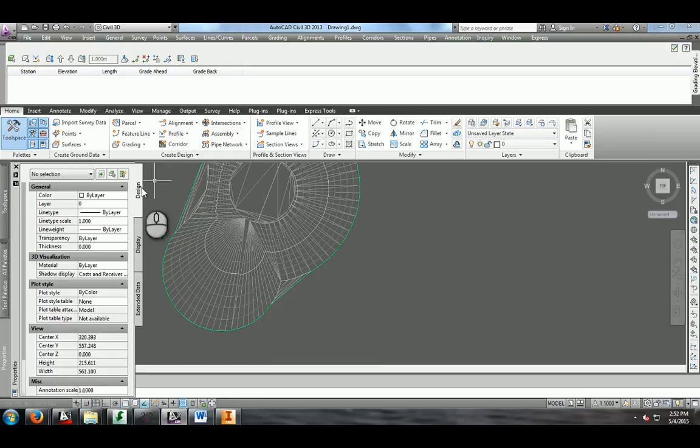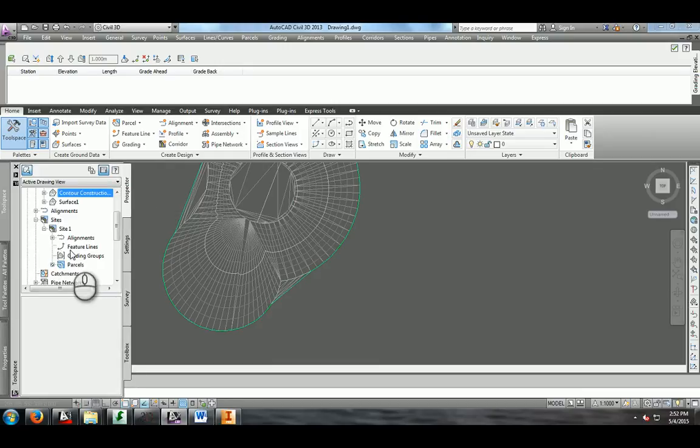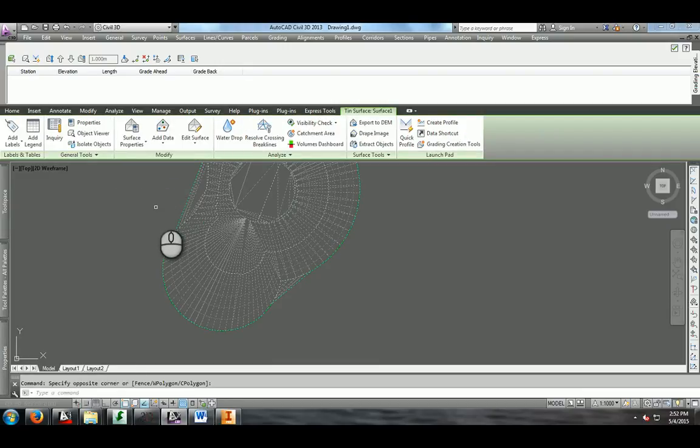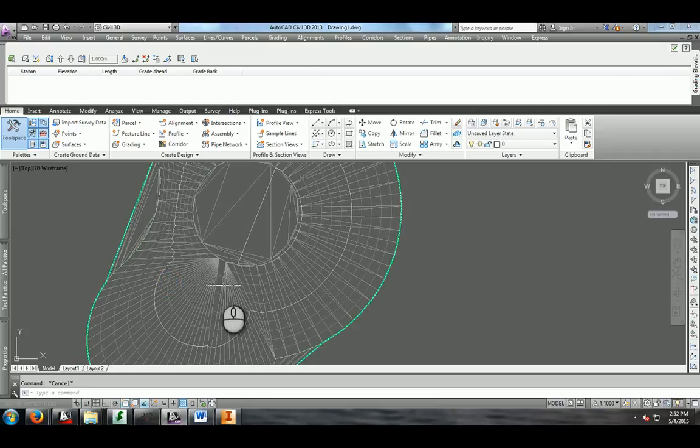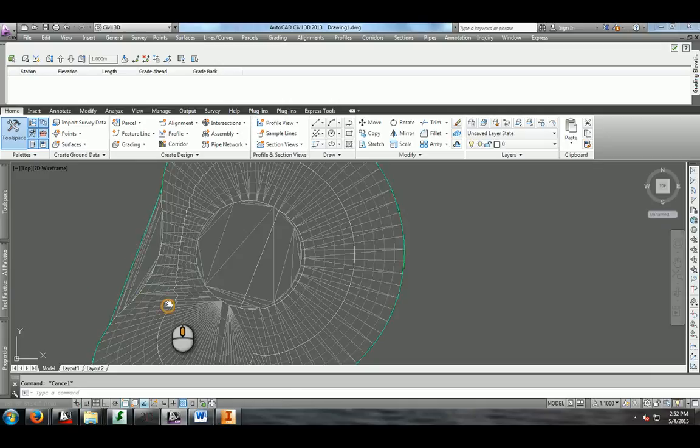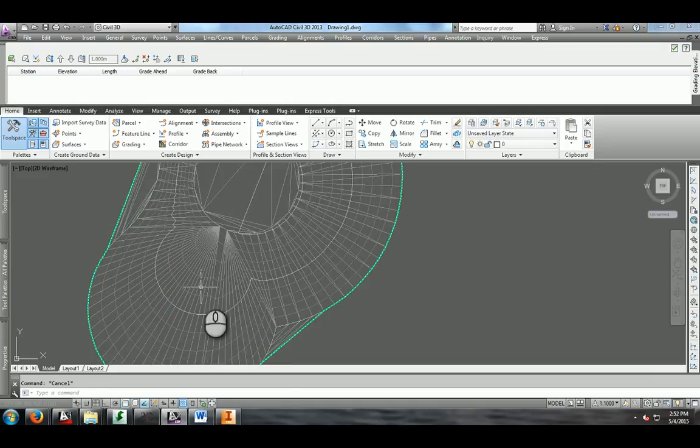So if I were to go to tool space, I'm sure you guys are getting bored of me explaining this, so I'm getting bored of explaining it as well. What I'm going to do though is show you why these triangles are long and generating contours where maybe you should elaborate more on what is actually supposed to be there. So I'm going to show you how to fix that. There's a few ways we can do it. We can add more break lines to the surface.